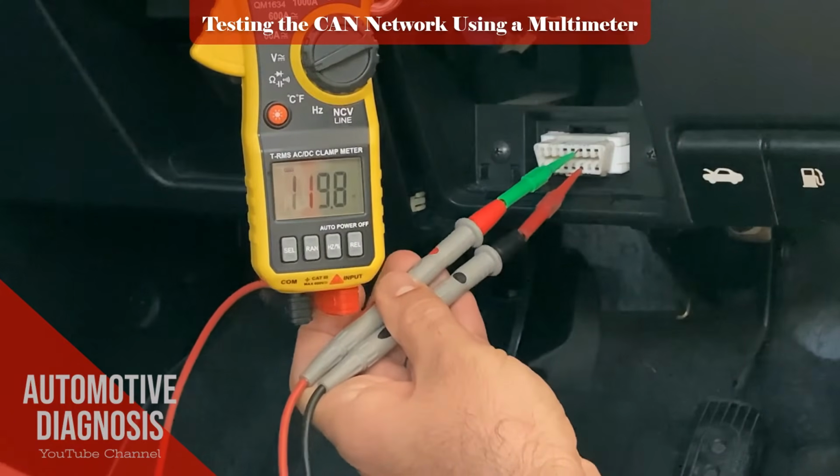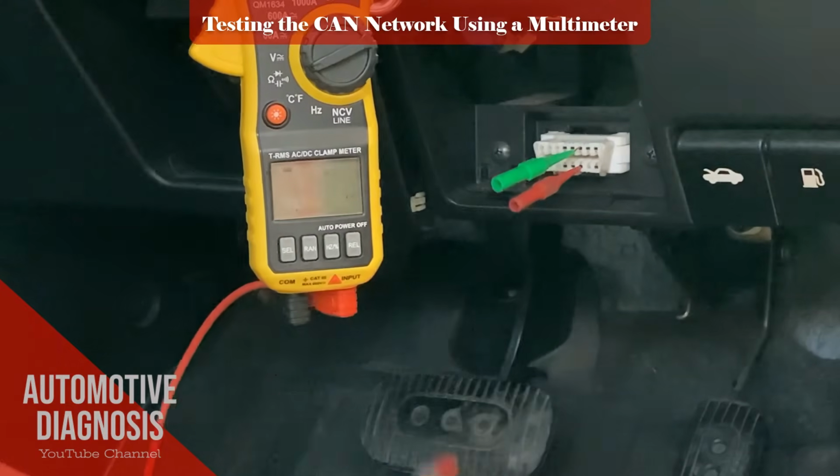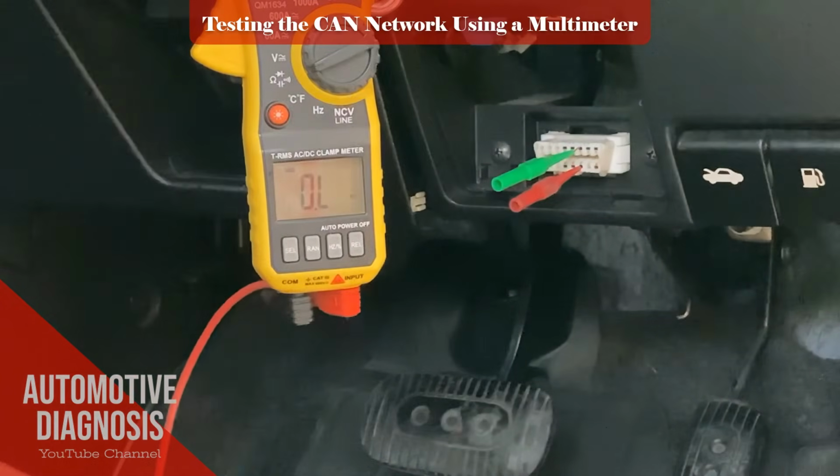As you see, now my reading is 120 ohm, which is just for one resistance, showing that there is an open circuit in the other one.